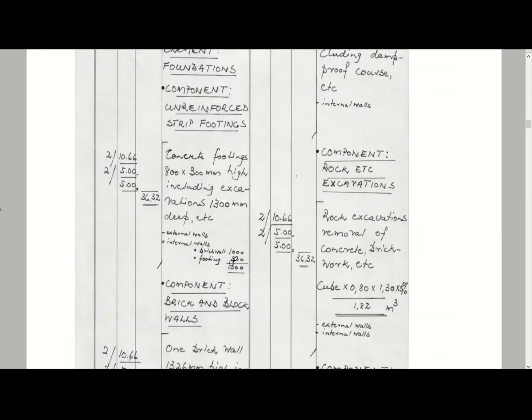So if you go to your dimension here, you will see there's a 2, and this little item there that looks like a divider item, or symbol, is in this instance a times. So you will see you've got your 10.66 times 2, and you will see there's a little line underneath that, so that just means that this is one item. So all of these items are added together to get to that point there. If there's no line in between, it means that the 10.66 should be times with the 5 to get to your dimension.